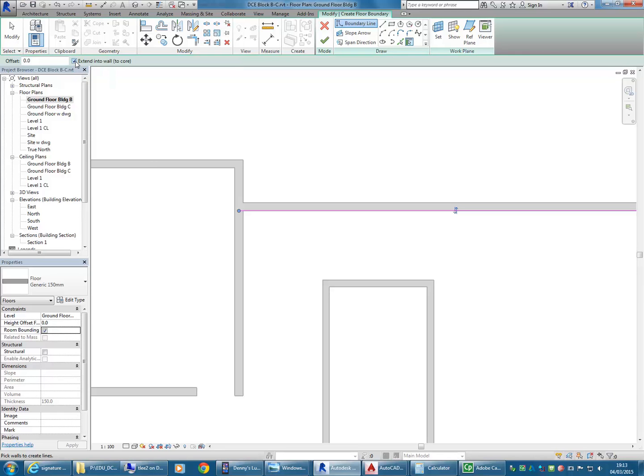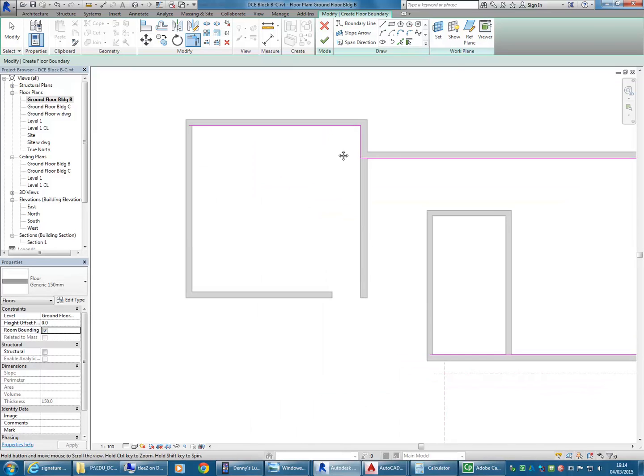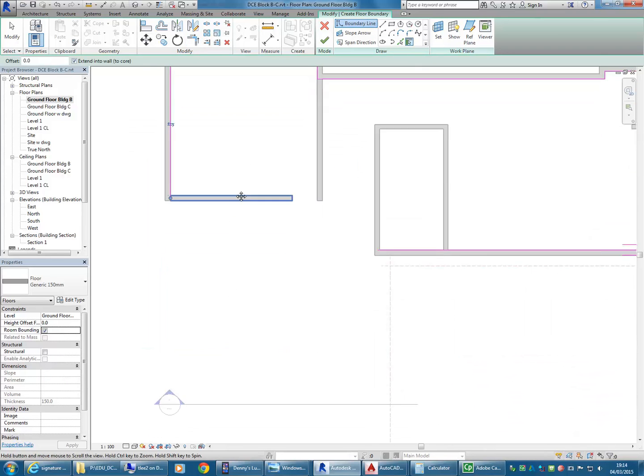So if you use those more complicated walls, you've got to think about how the floor connects to those inner layers, and you're just creating work for yourself. For an interior project, you just need it to look right from the inside. So just follow the inside edge of your wall, and with a generic wall, that's really simple. Once you start using all those components, it's great when you need to show construction details, but not if you're just doing it for a rendered perspective.